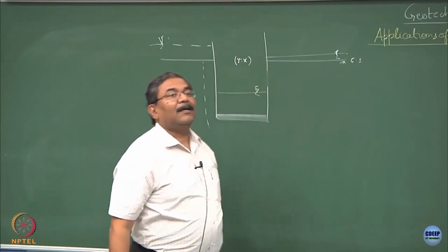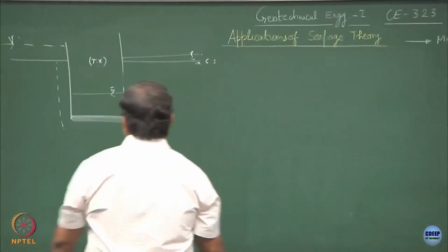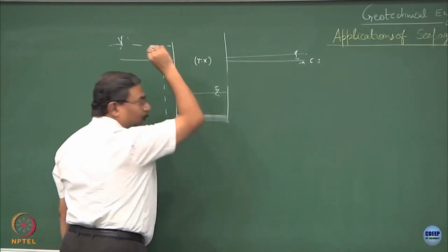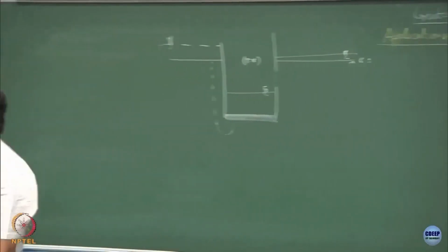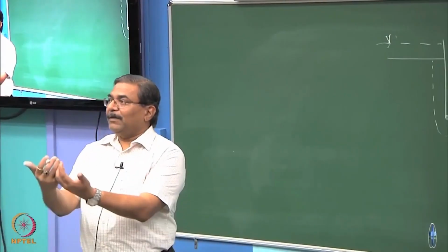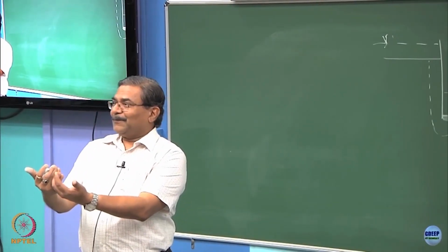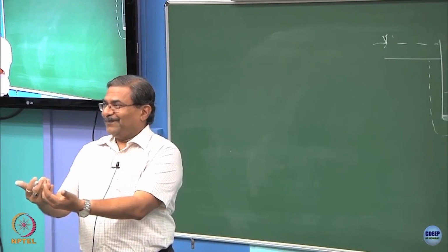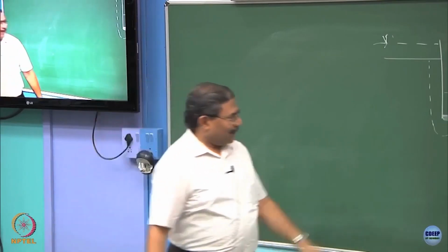The raft will get uplifted. That means, the moment this line comes and hits over here, what is going to happen? You are doing excavation, but the whole water starts coming in from the pit. Are you getting this point? This is what is going to be detrimental.